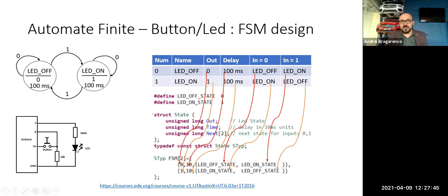With a different connection of the LED, we could have a different system. Let's imagine that the LED is connected not to the ground, but to the power. In this case, we are controlling the LED by 0 logic: providing 0 logic switches it on, and providing 1 logic switches it off.